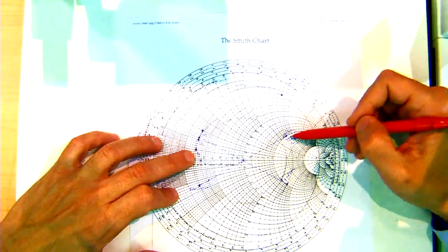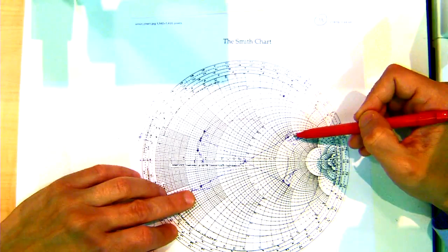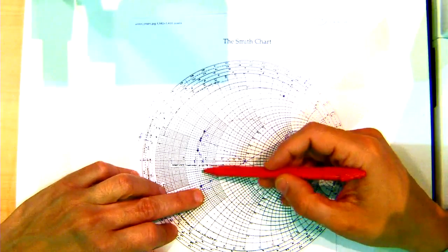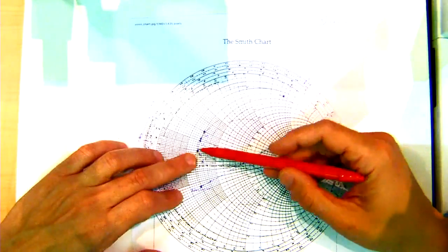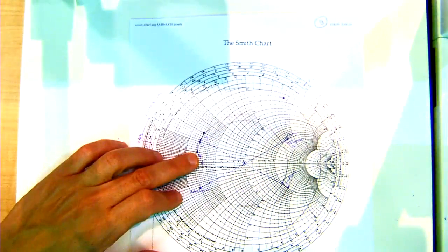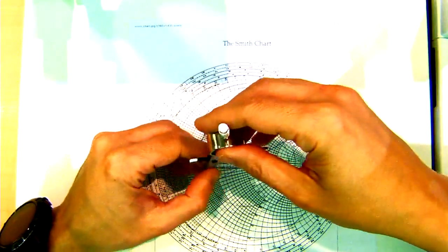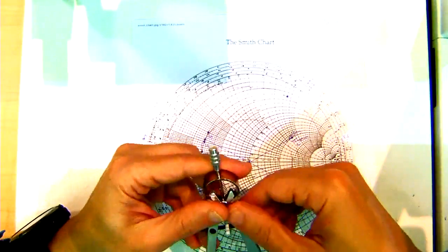Right, and then what happens is you find the admittance, and the length of that wire is now longer or shorter depending on the wavelength. Then, in order to work out how well you've actually matched that solution, you find your ZL and you then draw your VSWR circle.